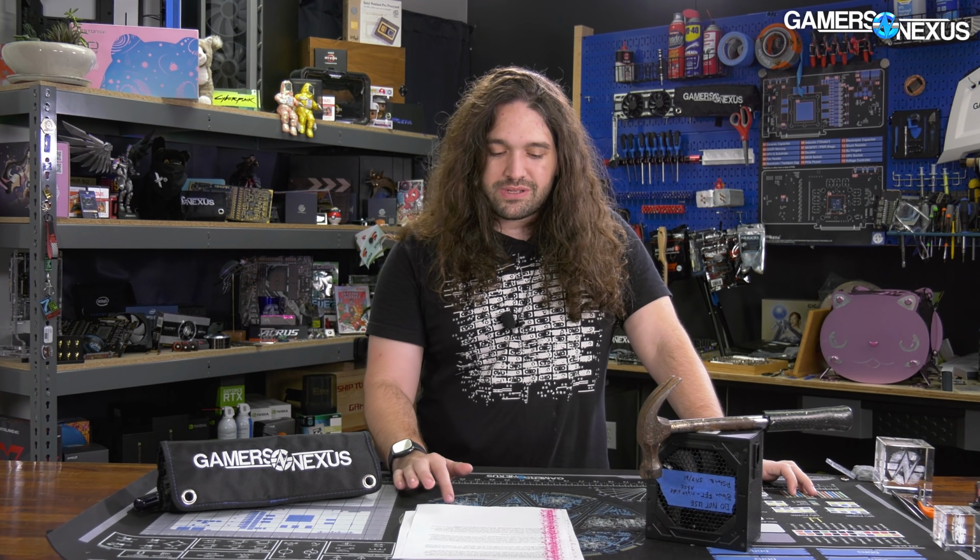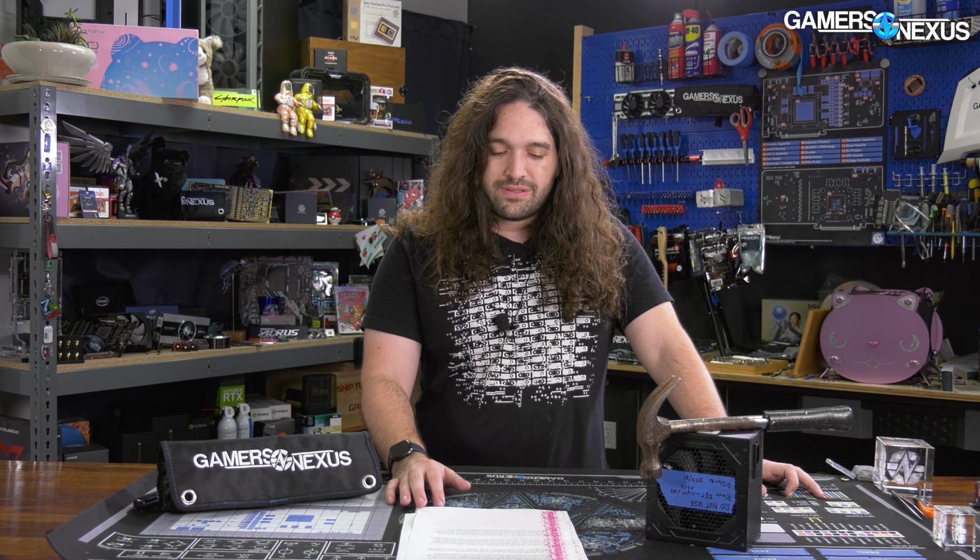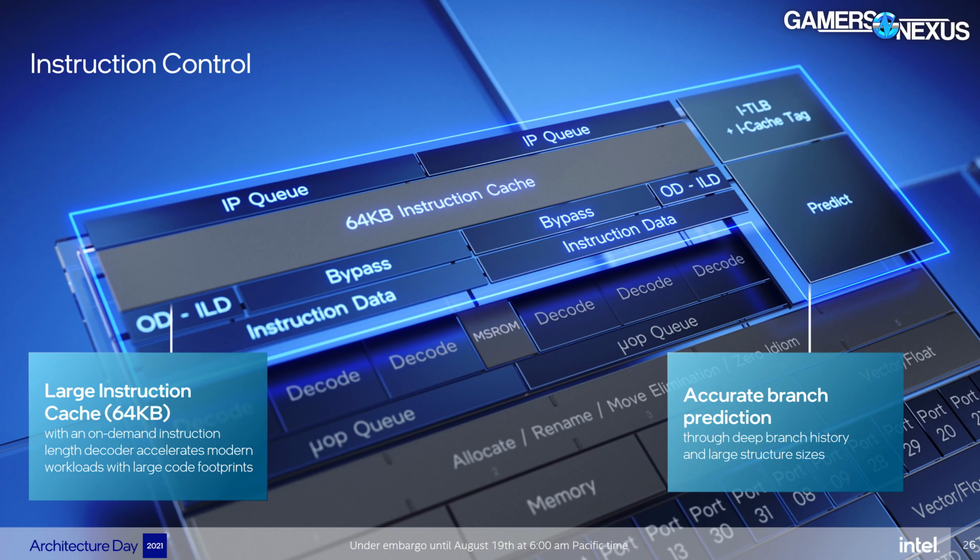And there were improvements. There were larger cache implementations, increased core count, sort of more of a linear scale there, but faster memory support, IGP updates. The process technology did improve, stayed 14 nanometer for pretty much everything, but did get some pluses at the end, and they were meaningful. And then die thinning for specific SKUs for better heat transfer for a bit. But the core, at its core, architecturally never really changed. The improvement numbers make more sense when the hardware is compared between the generationally different cores.